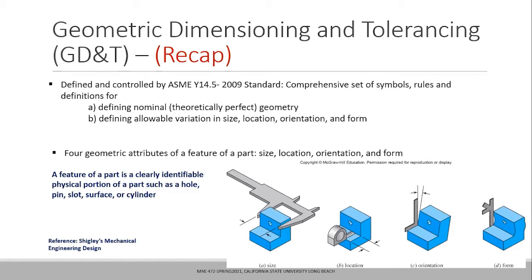And when I say more expensive, the reason is that you require very precise machining and very fine quality control. You have to spend a lot of time to inspect that the part getting fabricated is within the tighter tolerances and tighter restrictions that you are providing in the drawing. So the more tolerances, specifications, and controls you provide in the drawing, the more time it will require to fabricate it.